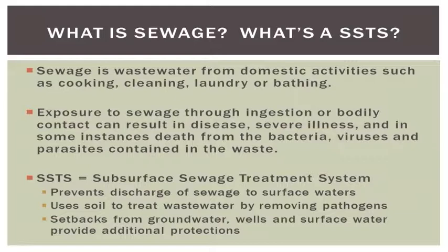When we use the term SSTS, that stands for Subsurface Sewage Treatment System. What that means is that it keeps the wastewater underground, it's subsurface. It prevents discharge of sewage to surface waters, uses soil to treat wastewater by removing pathogens, and then setbacks from groundwater, wells, and surface water provide additional protections, and we'll talk more about that as we go through the session here.